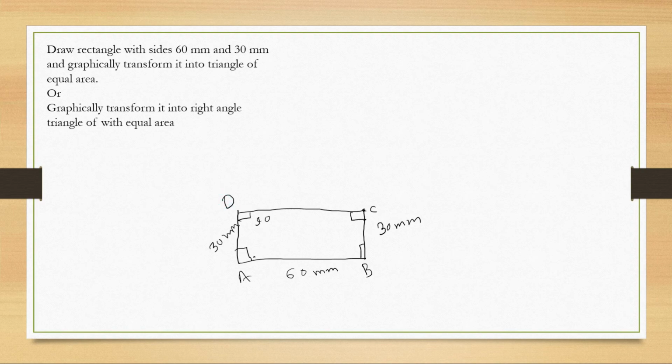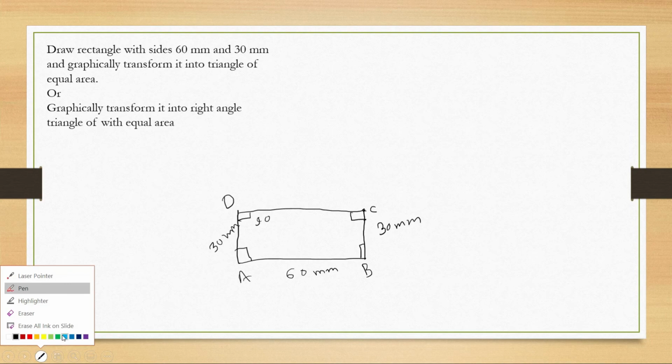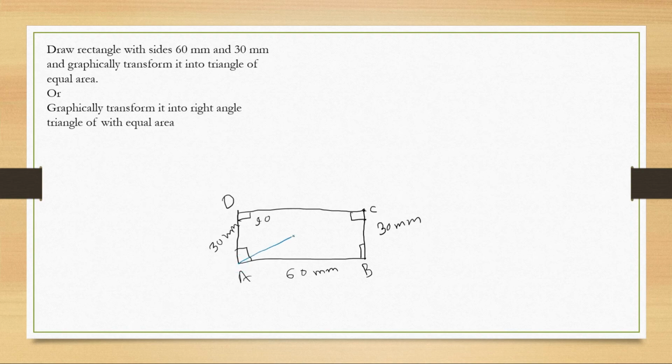Before showing you the actual answer, let me make my rough drawing of the answer here. Because all these angles will be 90 degrees, the diagonals AC and BD will be equal in length. So here we can use either AC or BD. But just for clarification, I'll show you how we do it like we did before. We connect the hypotenuse A to C in a straight line. Always use the drafter. Set your drafter parallel to line AC.